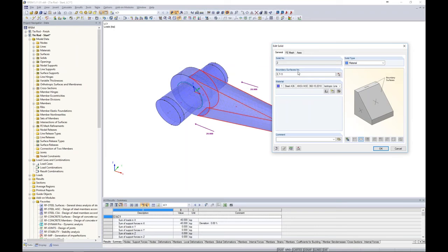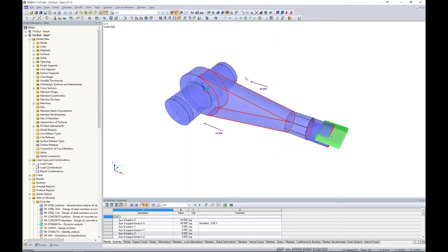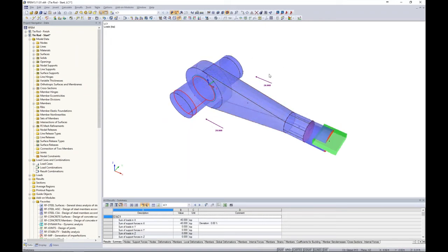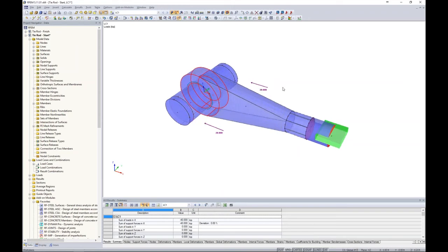You really can have any shape that you would like for solid and surface elements. Now, the bolt passing through the ring of this tie rod is also modeled with solid elements. And we even have our ring here defined by an additional solid element. So what we're trying to emulate here is this bolt passing through the tie rod ring. We have a load placed on either side to represent tension within that bolt.